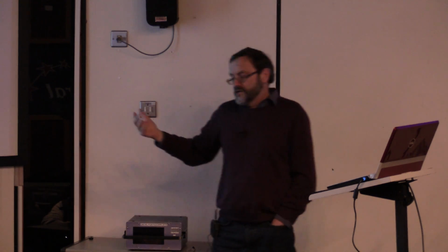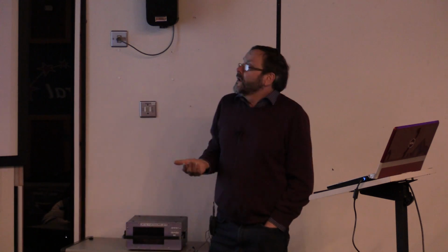We are on horizontal, which means you need to put 18 volts up the cable. And David has already mentioned PLL LNBs and the older type of DROs.